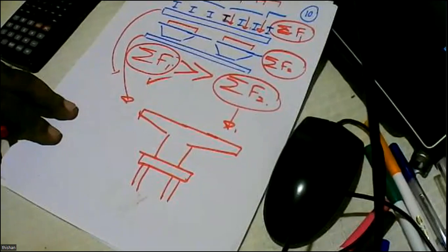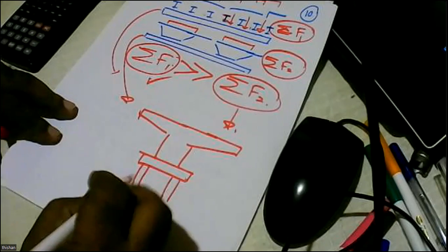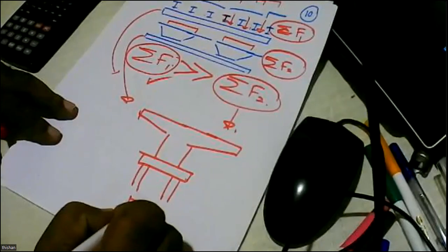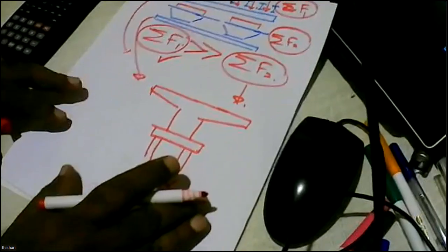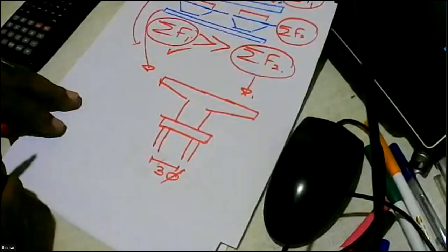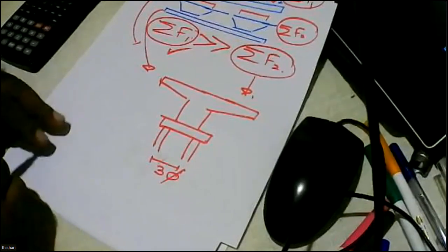So when you go with lesser number of beams, you can end up with lesser number of piles. When you have only few piles, and when they are at a spacing of 3 times the diameter, I think you don't have to consider the group effect.